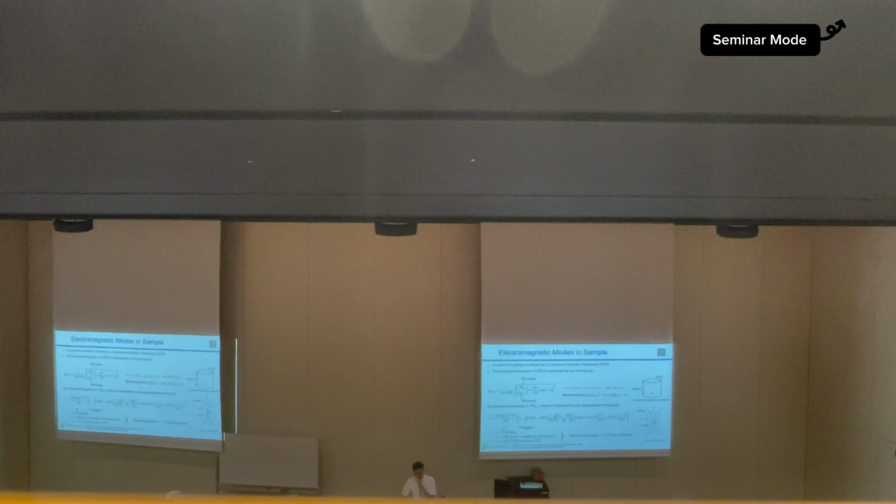If we set f as 915 MHz, which is the resonant frequency, and D, the height of the CDR, to 100 millimeters, and epsilon R equal to 18.23, which is the epsilon R of pure water at 20 degrees, then from this equation R, the radius of the CDR, equal to 70 millimeters is derived.